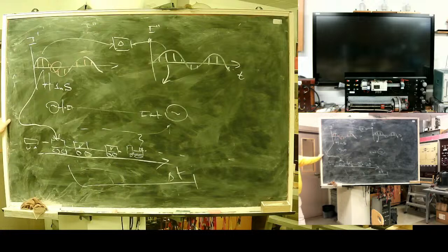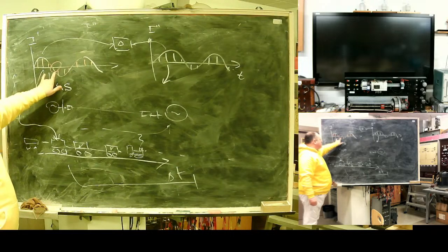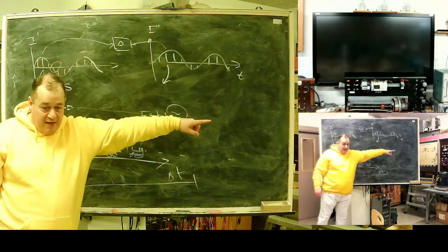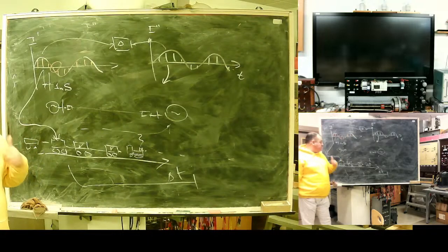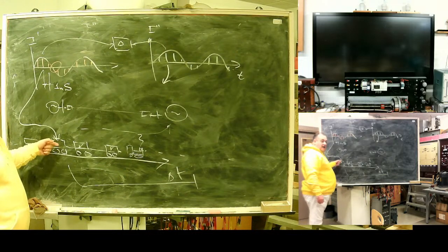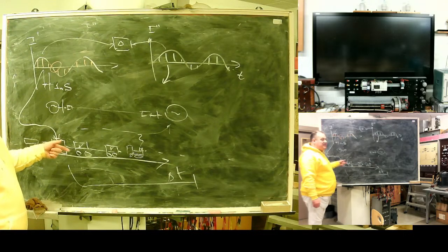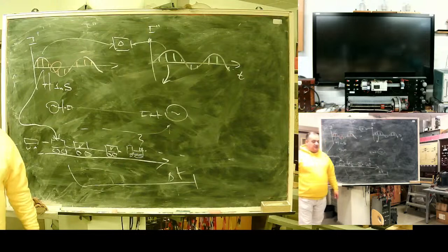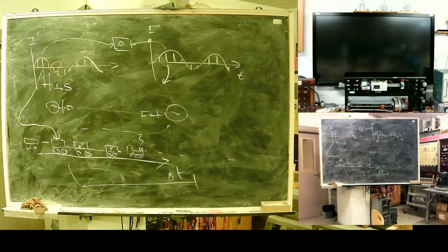It's a shift caused by propagation delay, because data needs to go this way and go back. If I own this communication cable, it's microseconds. But because I'm not the owner and I need to wait for my carriage, and I need data processing time, there will be some delay, maybe millisecond, maybe half millisecond, but it's always big.